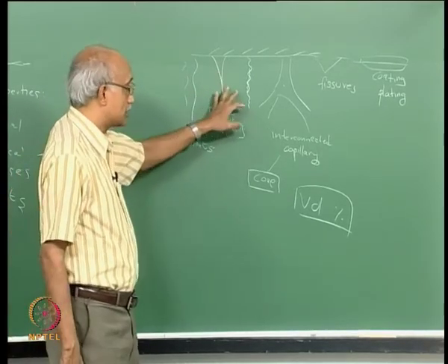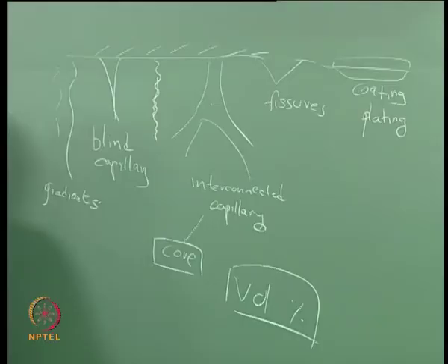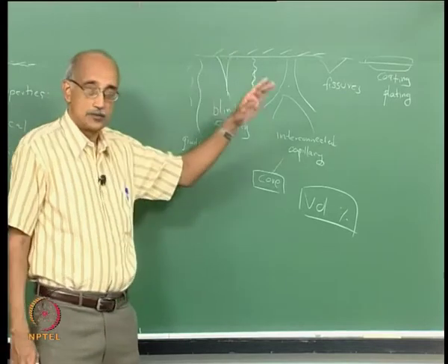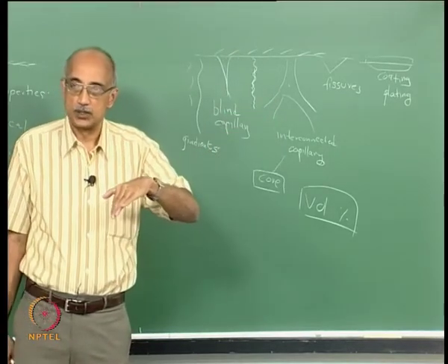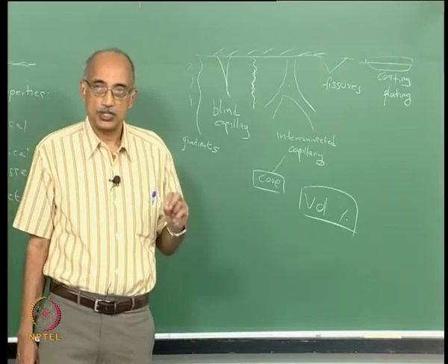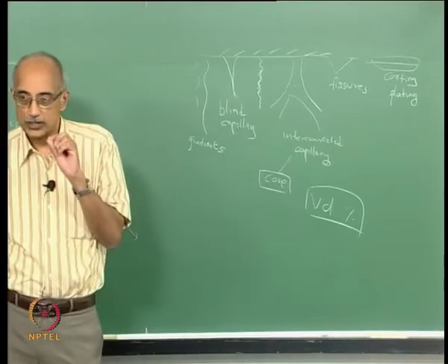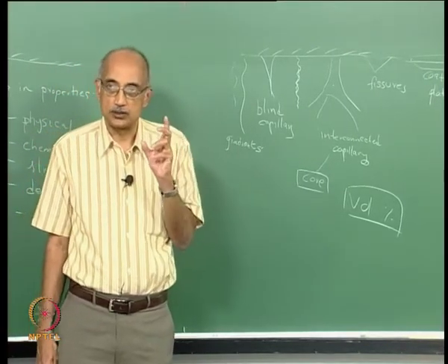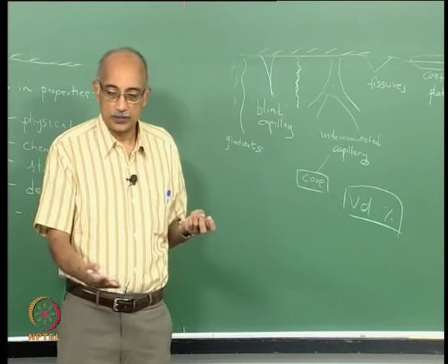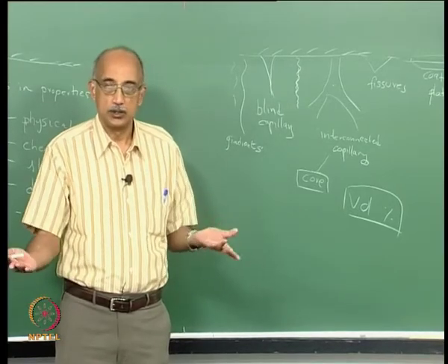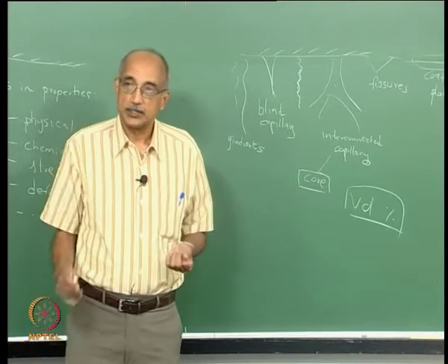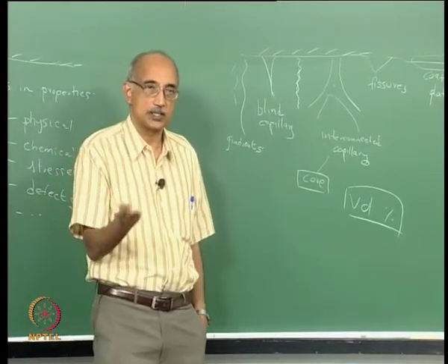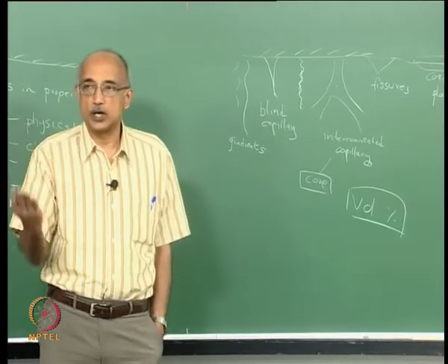Another important consideration is when you take a surface and you put down something on top of it like a plating or a coating, the surface itself now becomes part of the subsurface. So that is something that is important to appreciate, that our definition of the surface must be consistent regardless of its composition. If you have, for example, a steel table that has nickel plating on it, then the surface is not steel, it's nickel because that is the surface that is exposed to the surrounding fluid.